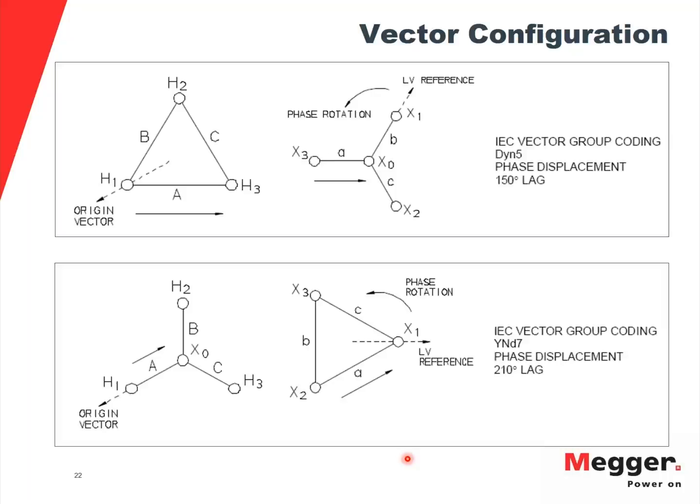First, the TTR test, where you get your turns ratio and can compare it to the nameplate. And of course, if you have factory test values and commissioning values, you can compare to those. So you have a direct, on-the-spot comparison all the time with the nameplate values.